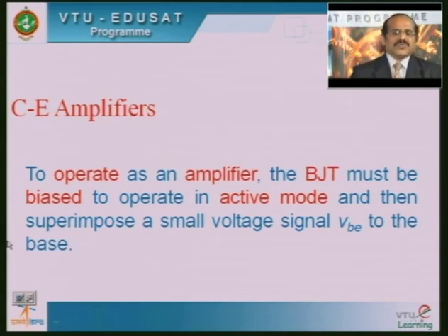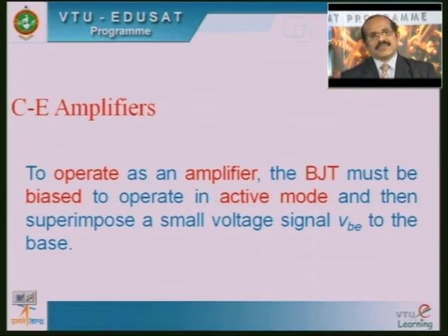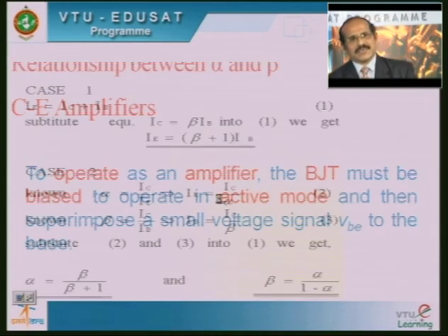And you know that usually to operate a BJT amplifier, we prefer the common emitter configuration. It is only because this will provide more current gain as well as more voltage gain. And also it should be noted that to operate the BJT as an amplifier, we make use of the active region, where the output characteristics are linear and an equal distance exists between the neighboring curves here. Which is very important as far as faithful amplification is concerned here.